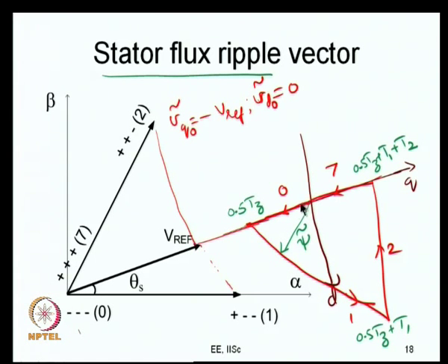So, you see that this vertex of the triangle and this vertex of the triangle are equidistant from this origin, which you may call O. Now, this is the case with the conventional space vector PWM. If you are using, let us say, something like sine triangle PWM or some other third harmonic injection PWM and so on, then, within the limits, since sine triangle PWM is applicable only up to a certain amount of fundamental voltage, let us consider within that limit.